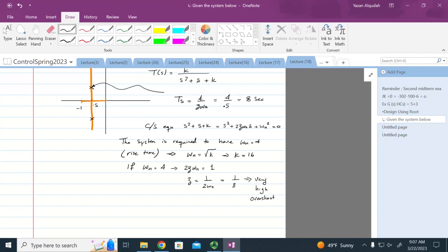Again, the root locus gives you some flexibility. Looking at this root locus, when k is very small, I'm operating here, overdamped, critically damped, and then underdamped. That's about all the responses that you can control. It's underdamped with a settling time that is going to equal 4 over 0.5. If I increase k, I'm going to get higher overshoot. And that is the flexibility that changing only the gain on the root locus is going to give you.